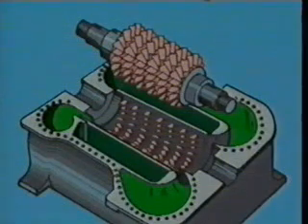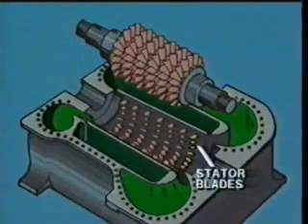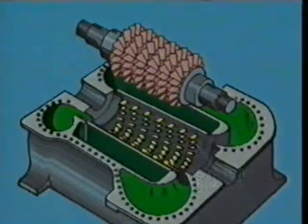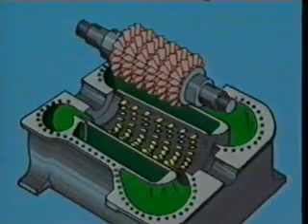After the spiraling gas moves through one set of rotor blades, it passes through a set of stator blades. Stator blades are stationary and attached to the casing. They act in a similar way as a diffuser by decreasing the velocity of the spiraling gas and increasing its pressure.